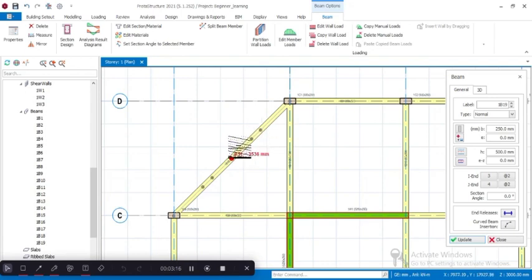Click on 0.67L. That's the start point of the secondary beam. Place the cursor on the destination beam. This is another 0.67. You can see that it's aligned. The same thing goes on all the beams. You can see the snap points on the beam and the perpendicular also. The perpendicular here is 0.67 on both sides.